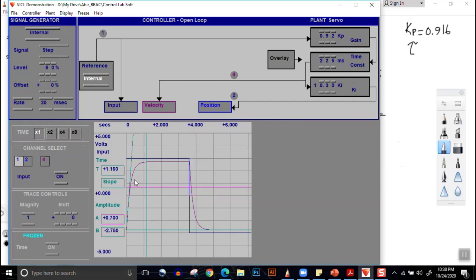So we have found the 0.7 line, and we take the time at exactly the place where the value of output is 0.7. Again, I'm saying it was not supposed to be 0.7. It was supposed to be 0.715. But since the resolution is low, it still gives more or less a good approximation.